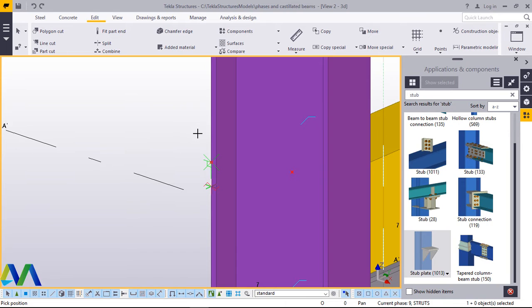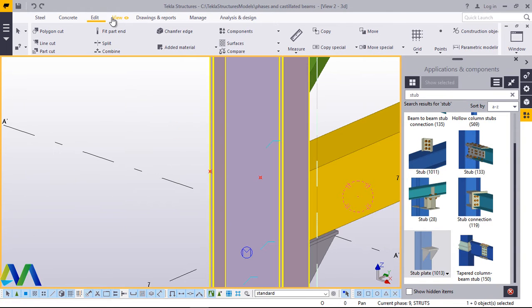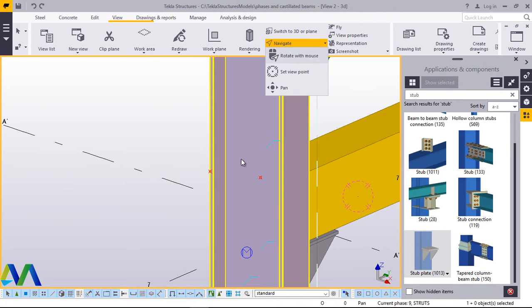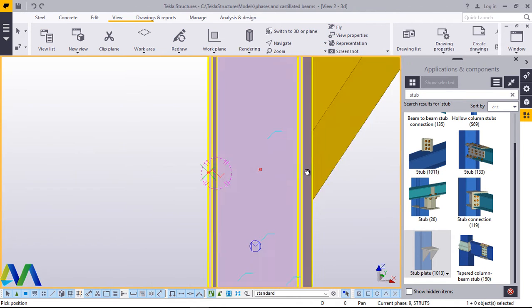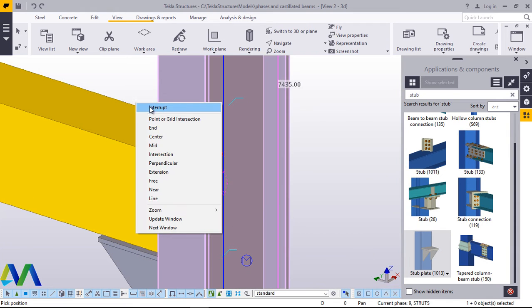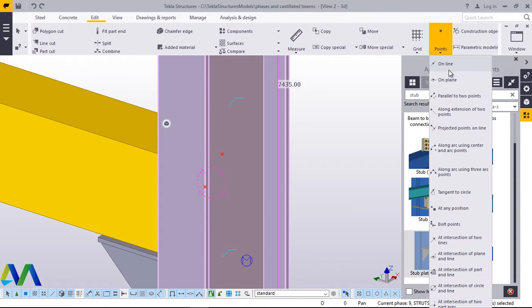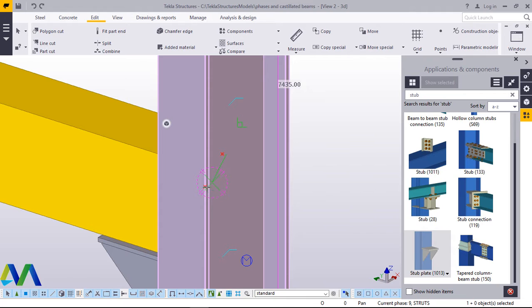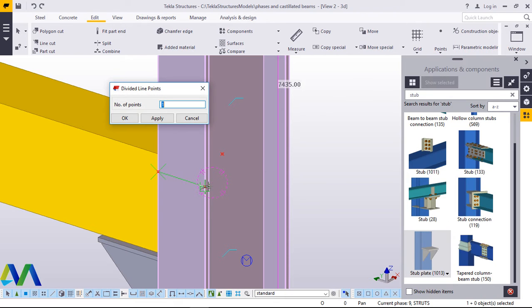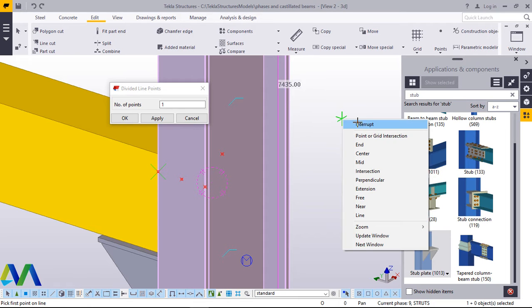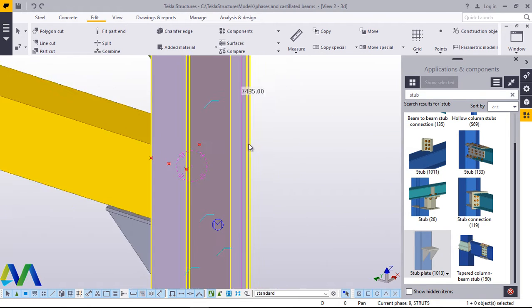Having done that, I need another spot on the other end and get the midpoint between the two. I'll come to navigate right there. I'll rotate this, then come to edit, any position from here to there. Right click to interrupt for an exit from that command. Then I'll get the midpoint between these 2 points right there. Perfect. I'll interrupt and close that command.